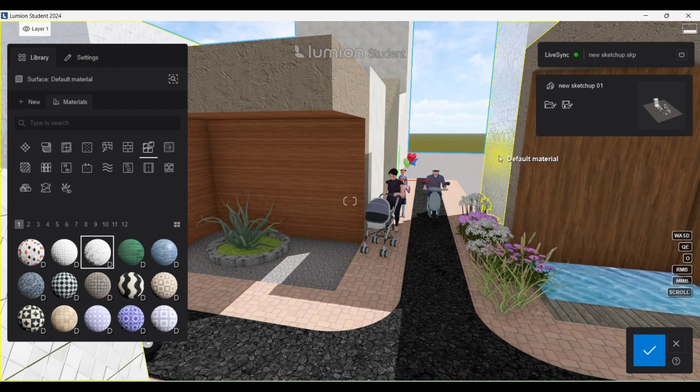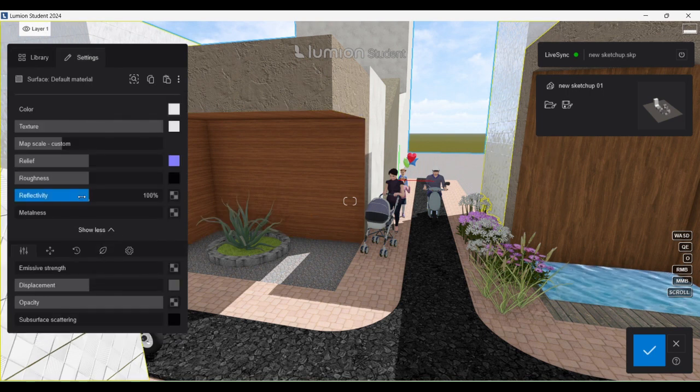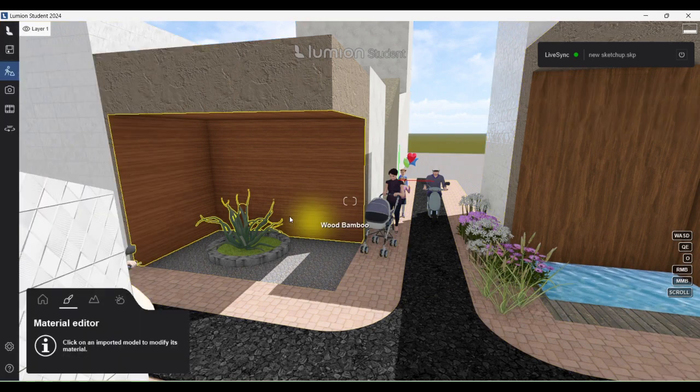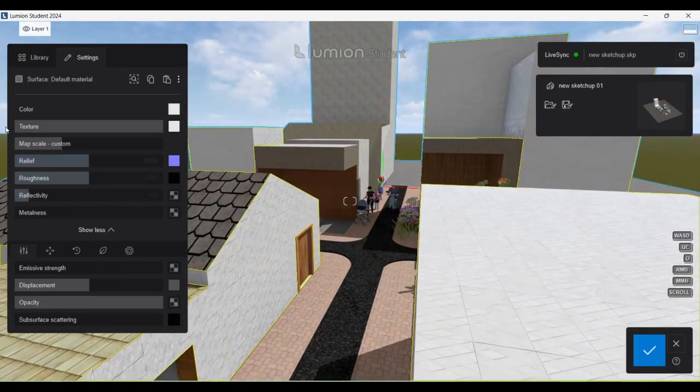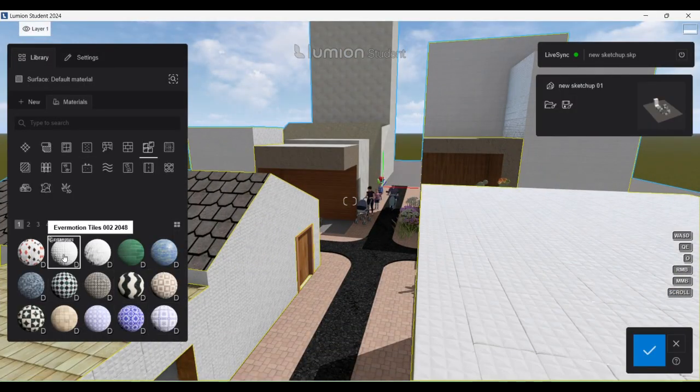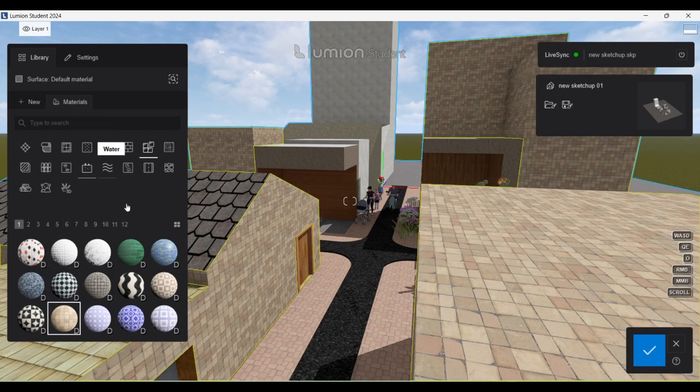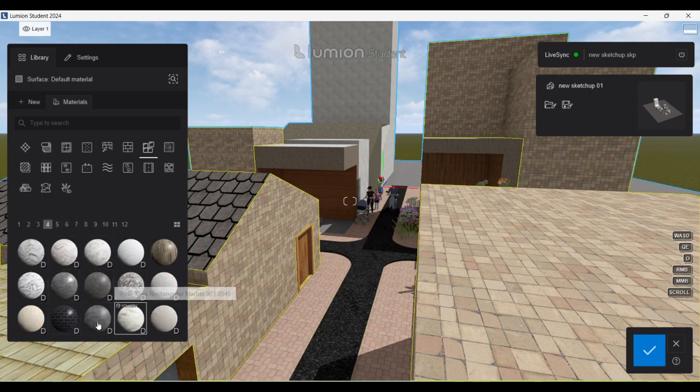And then you see, everything just changed because all of this was in one color. So if you don't give separate colors in SketchUp, you cannot give the particular designated materials in Lumion, and there's no way to change that. You'll have to change that in the SketchUp software. So anyway, we won't be seeing the roof view, so this is fine.